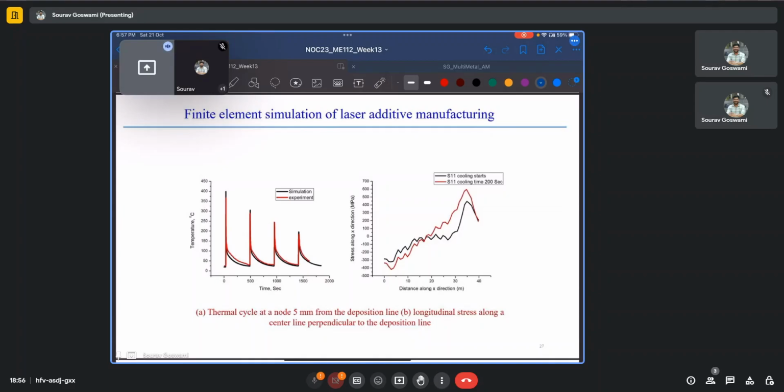So one of the commonly implemented techniques is to actually match the thermal cycles. So here to the left, you see the thermal cycles for such an AM process. And I also discussed somewhat about this in one of my slides, where I explicitly calculated the thermal cycles using the ANSYS additive package, and we saw how they vary.